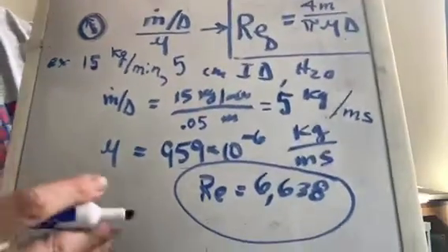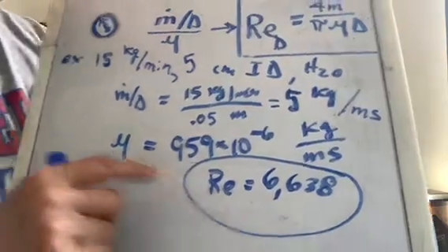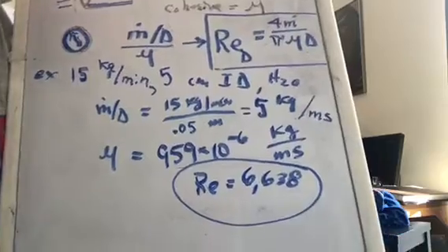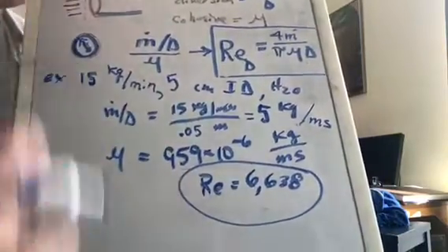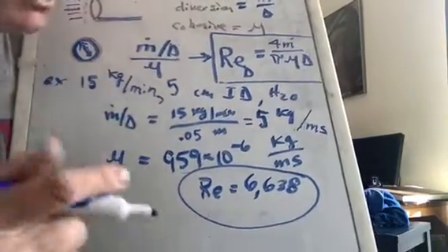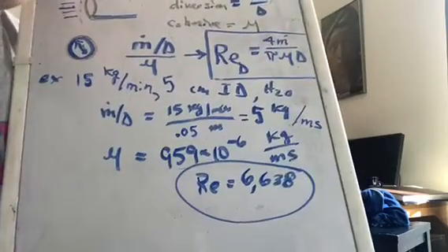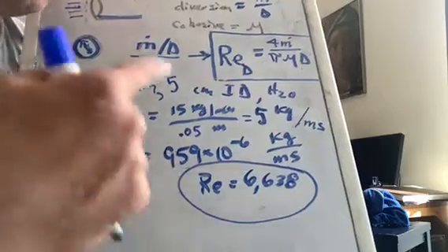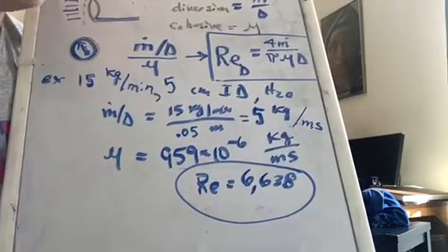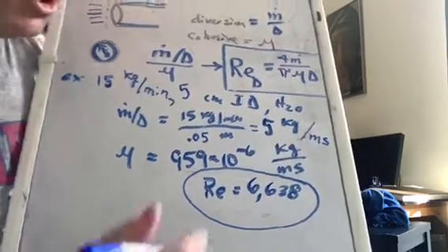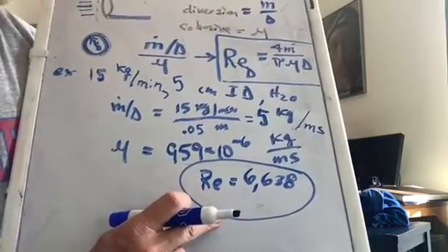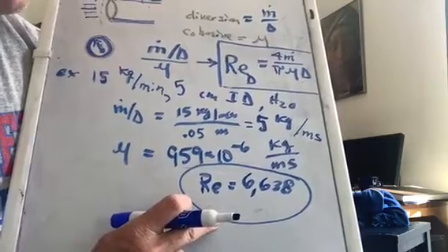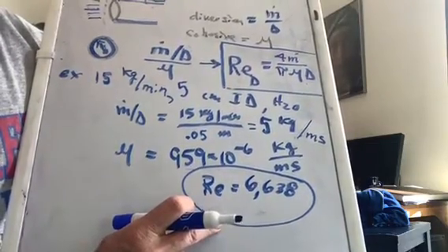It's a very interesting thing that we can come up with a calculation for a geometrical situation that will tell us whether it's laminar or turbulent, whether we're doing carbon dioxide, water, air, honey, glycerin, etc. And the cutoff we usually have is below 2,100 is laminar, above 4,000 is turbulent, in between is termed transitional. So we definitely got turbulent flow in this case. And we might even be able to lower the mass flow rate some and still get turbulence.